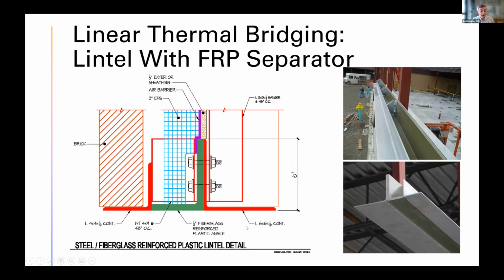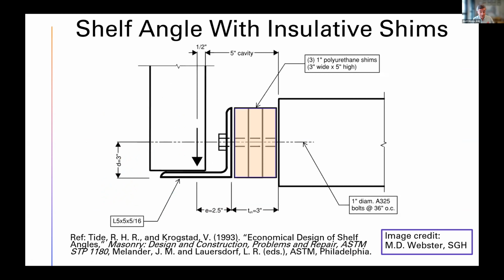It looked pretty good. But again, like Rob said, thickness matters when it comes to mitigating thermal bridging. The other thing for passive house and all kinds of buildings is it provides a good place to allow continuity of the air barrier, which structural engineers also need to think about as it impacts their structural details.